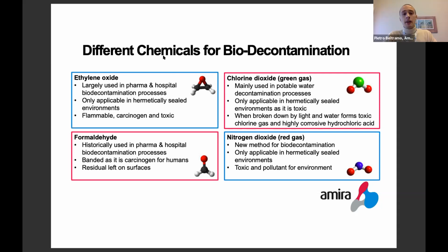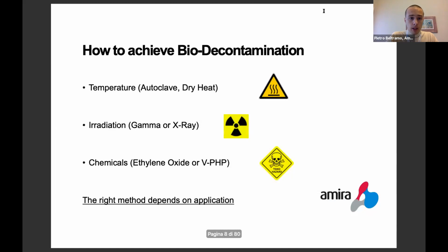So basically, there is no real regulation that tells you exactly which one you should choose. Again, from my point of view, it's like the autoclave or the gamma radiation. There is no regulation that tells you if your sterile garments for the clean room should go into the autoclave or to the gamma radiation. But you cannot put the garments, the clothes, into the autoclave, they will be destroyed. So you go for gamma radiation. So one thing is the logic.